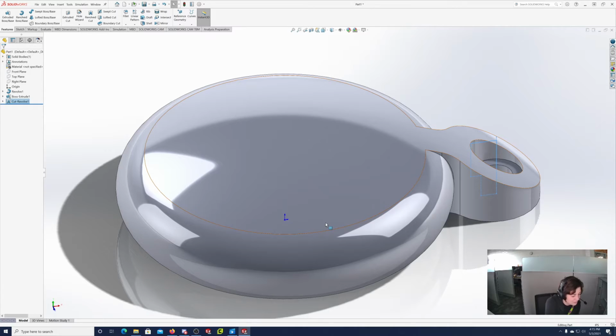All right. So now we're going to do the circular pattern, and this is kind of the fun part here. So let's see. We should be on page 7-28, step 7. We're going to go to the circular pattern, which is below linear pattern here. So if you are in your features tab, go over to linear pattern, use that little down arrow and click circular pattern.